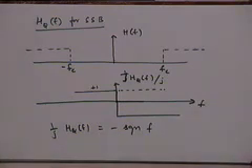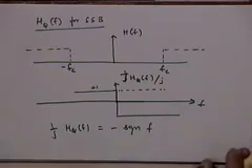So as expected, this theory leads us to a filter HQF, which is nothing but the Hilbert transformer for the case of SSB, right? For the VSB, the filter would be slightly different. That's about all. Let's look at what the filter will be in this case.